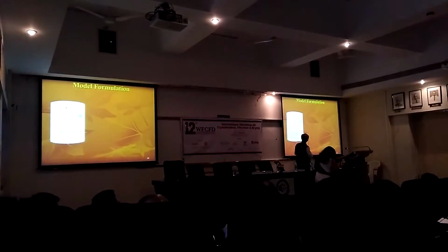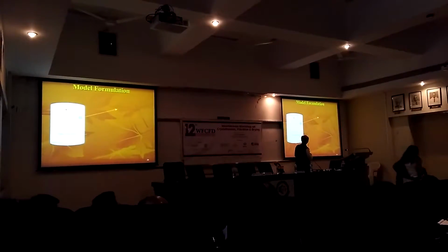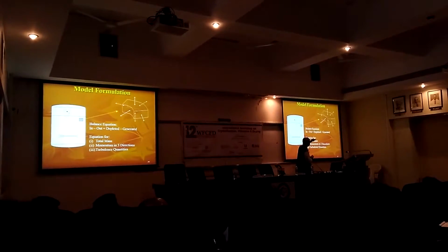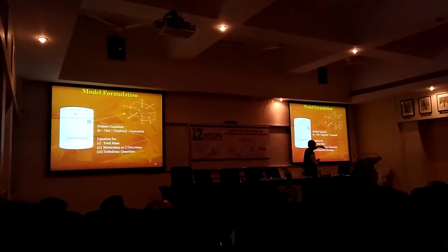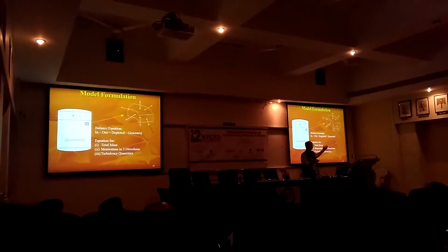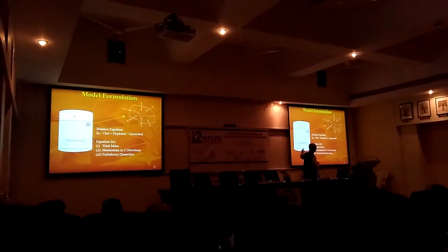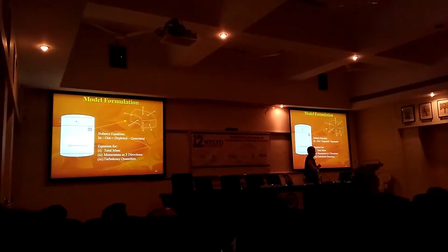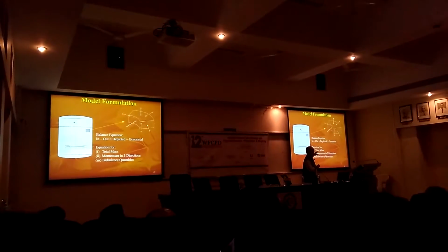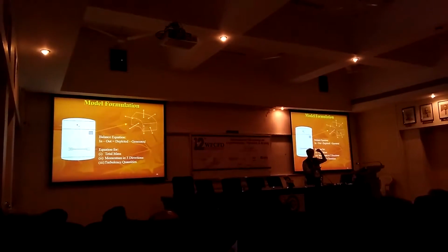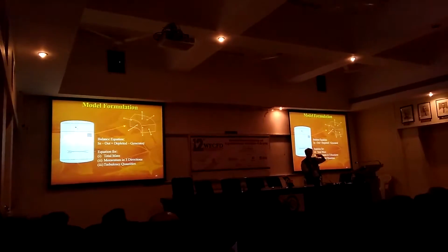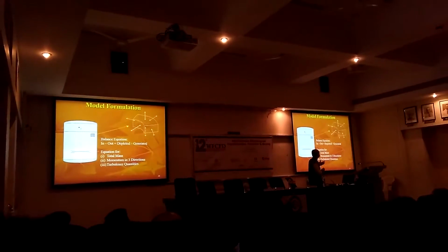And this is, you imagine a fluid element. The fluid element is exploded out here. Some liquid is going in, some liquid is going out. It has certain solid particle suspension in it. I can solve these Navier-Stokes equations for total mass, for total momentum in 3 directions, and the turbulence parameters, which are ultimately going to decide the solid-liquid mass transfer coefficient, which in turn decides the growth rate of the nuclei which are present in it.